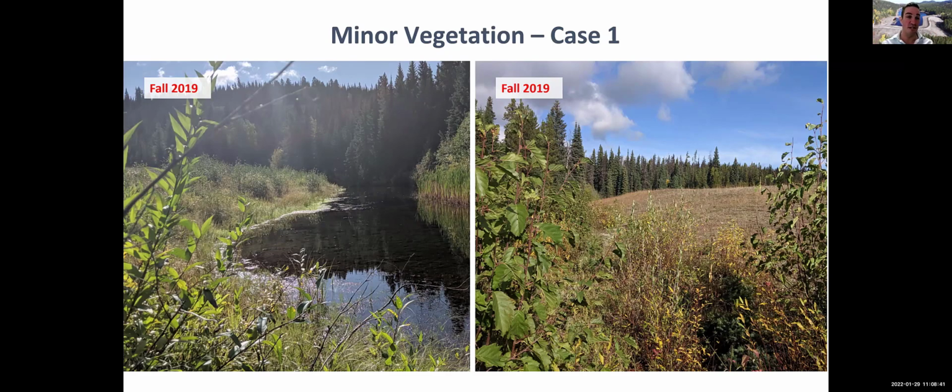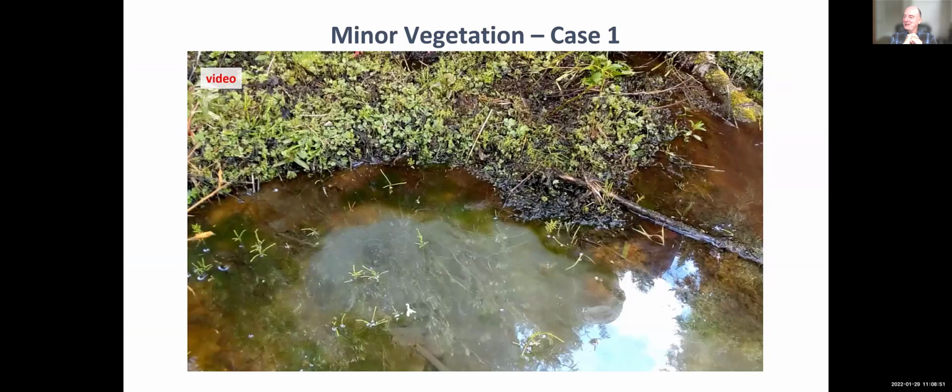Essentially, the one on the left flows to the one on the right. They do measure seepage and they do quite a bit of manual inspection, walking up and down these. And you can see it's quite hard to do inspection with that much vegetation, though, isn't it? Well, and that's just it. My inspection found quite a few things and quite a bit of seepage, and identified that this is a potential seepage area that is of concern. And we'll talk a lot about backward erosion, types of erosion in the next webinar. But the client there took that advice and decided, I'm going to keep on top and keep looking at this. And this is what he found.